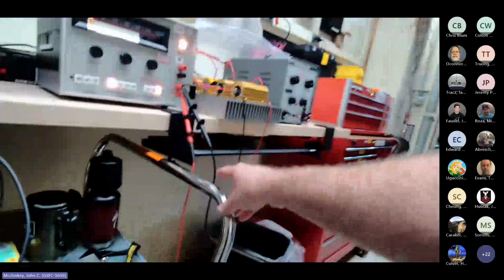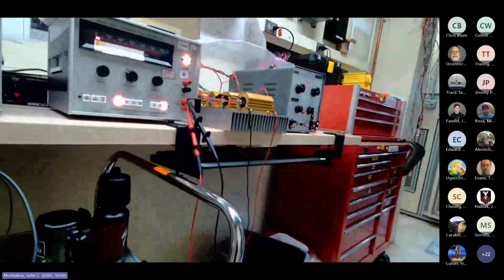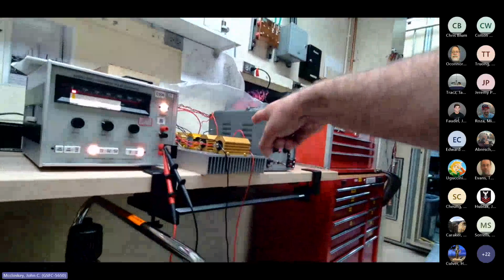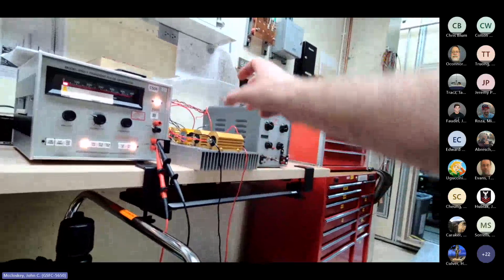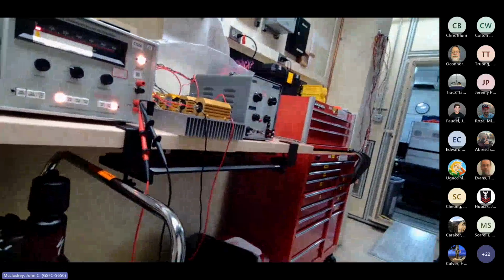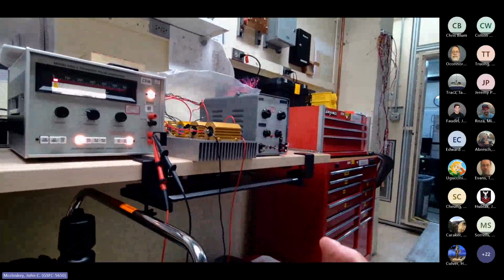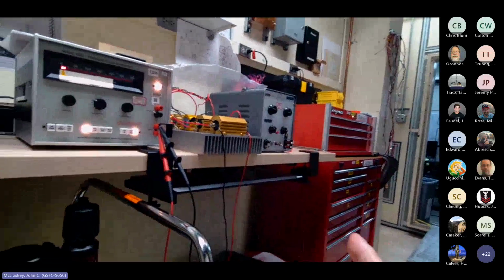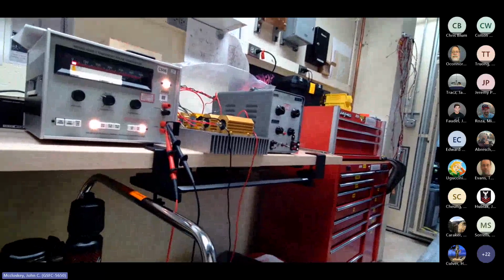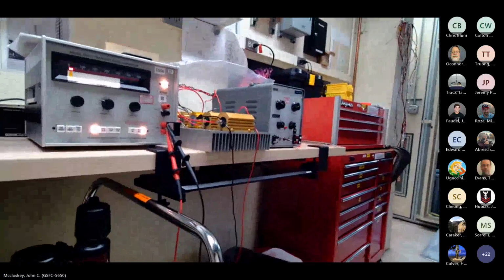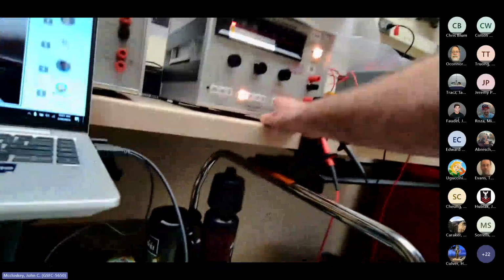You could use the wires that you're going to use in the actual connection to the EUT. Go to this load resistor for your pre-cal, then just disconnect from the load resistor and hook up to your setup going to the EUT. Because the 10 microsecond pulse is slow enough that it's not going to be as dependent on the specific interconnections, right? But if you're going to go with the 150 nanoseconds, so let's go back to that.